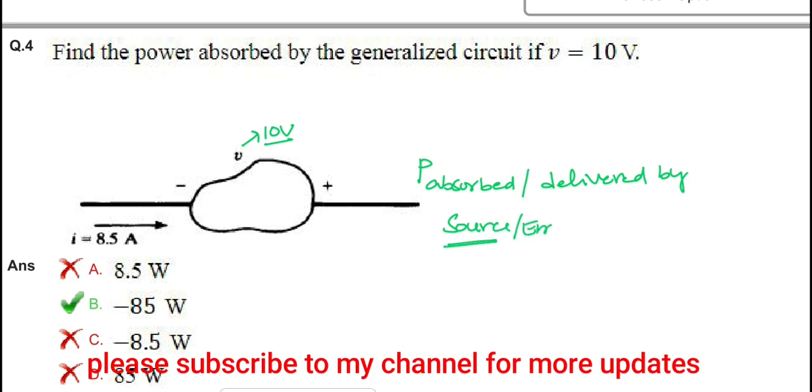Our source or EMF is always negative. Now it is a source, acting as a source here. The source means current entering from the positive terminal. As per the sign convention, the current is leaving this node.